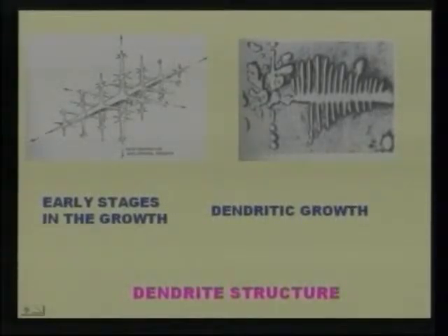Why is it called dendrite? Dendron is a word from the Greek. The meaning of dendron is tree. The grain structure is developed like a tree, stems, and other stems are formed. These crystals are absorbing the smaller crystals and forming bigger crystals. Like that, it is developing as a tree. The heat dissipation will be taken in all the directions and towards the smaller crystals.